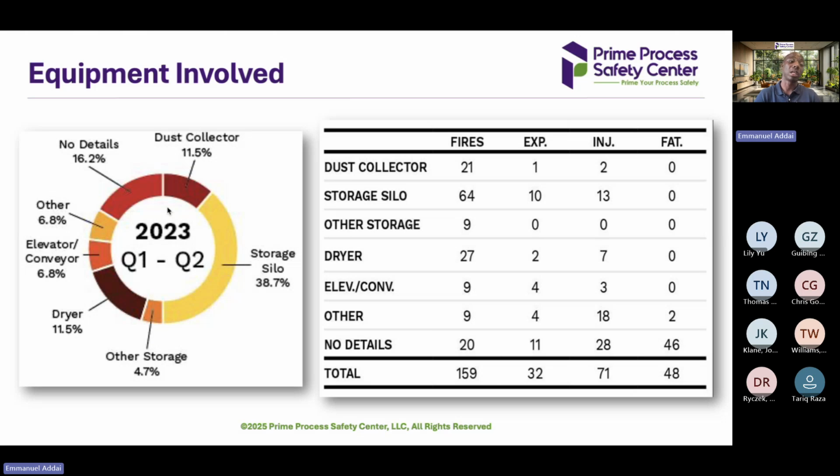And for dust collector, I think this year I also investigated an incident in Houston for a dust collector explosion. Normally in the dust collector, the finest material goes there, and with various ignition sources, maybe the filters, if not bonded and grounded, can lead to electrostatic discharge or upstream ignition sources and can lead to an explosion in a dust collector.